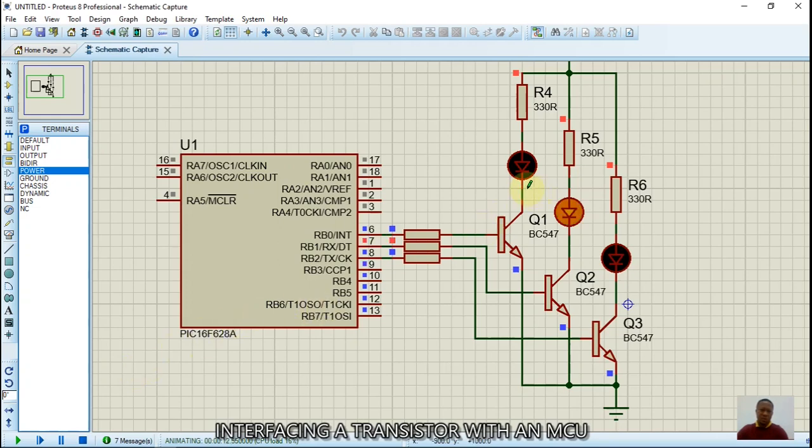See, our first LED is not coming up. You have to go and check why. You have to go and see why it's not coming up from our program. Port B.0. You see, the program we wrote did not really go well with the design, because the ports we chose in this design is not exactly what we chose in the program. That's what I was telling you earlier.